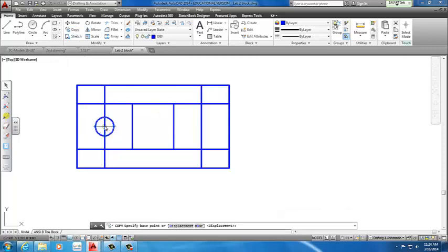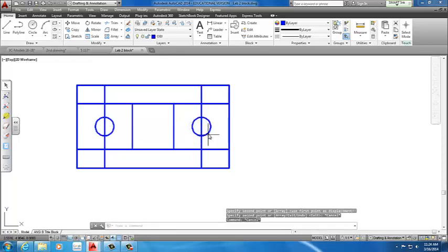You select the center of that circle, and you just copy it over to enter. Recreate exactly that. Make it perpendicular when it hits that line, because that is the center, the midpoint of that line. Looks way better than before. So now we have that keyhole. These lines can be deleted. They were just there for reference.